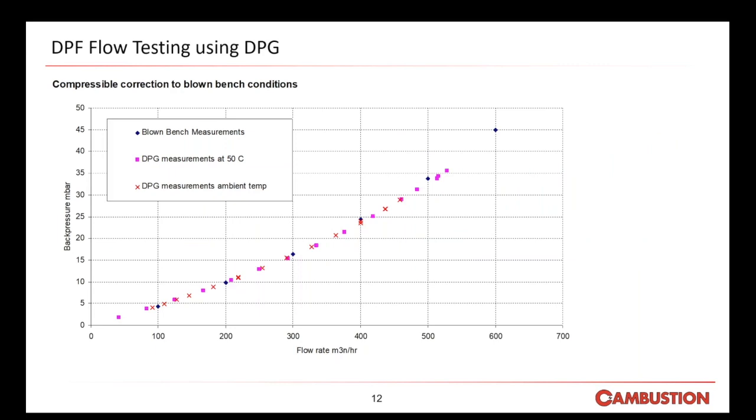So the DPG can be operated as a flow testing rig. Often our customers have a blown bench rig, which is misleading. It's normally actually a suction bench, and we have the ability to correlate one of these to do equivalent flow tests, normally over cold flow sweeps.